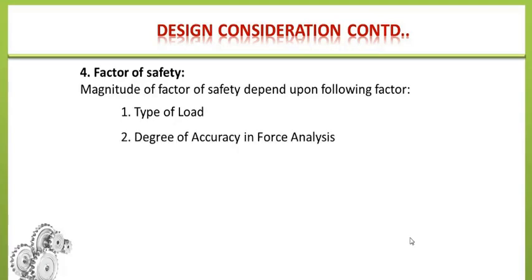Then, degree of accuracy in force analysis. So this is again very important. When the forces acting on the machine component are precisely determined, I already told you about that, with no ignorance of even a very small amount of forces, you have to determine all the forces precisely. If the designer completes that work very carefully, then you have to consider low factor of safety.